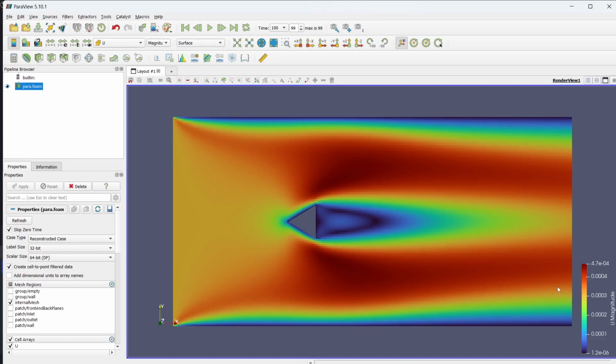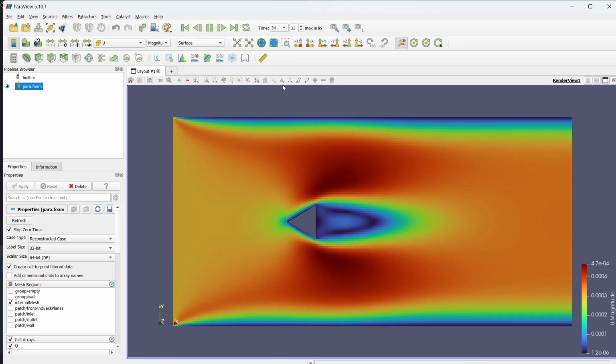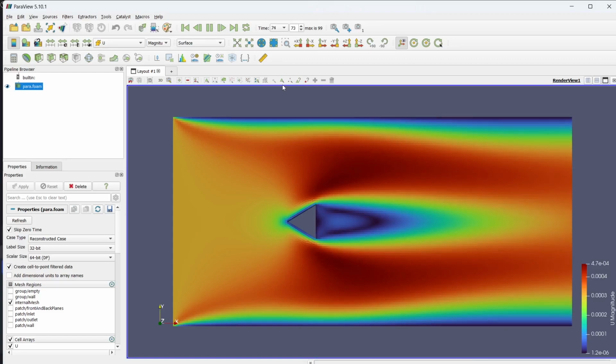This is a steady state simulation, so only the final time step where the solution is converged is useful, but still in OpenFOAM we will get a simulation of all the time steps, which can be seen like this. This is the simulation over all the time steps where the solution was made. In the final result, in this case, we have the final steady state flow over the prism. So we will see how to make this geometry.